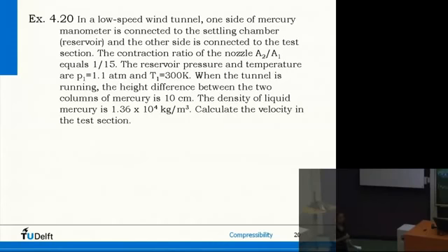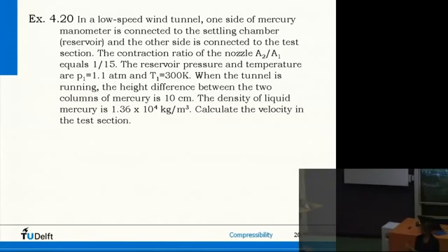Equation of state, perfectly. If you think about the isentropic flow relations, P over P and T over T, that's really for compressible flow, where you have significant temperature changes. In incompressible flow, you typically don't have them. So the one I used before for the supersonic wind tunnel will not get you anywhere. But the equation of state, P is rho RT. So if we know somewhere pressure and temperature, we can find the density.